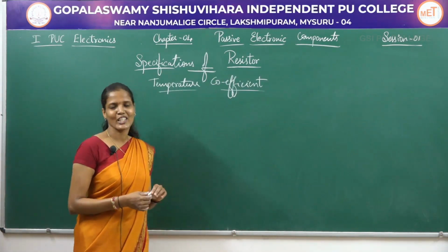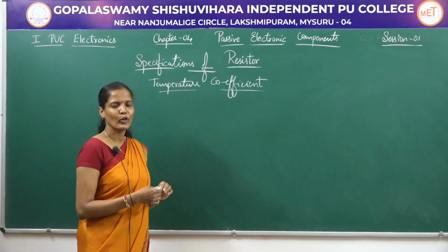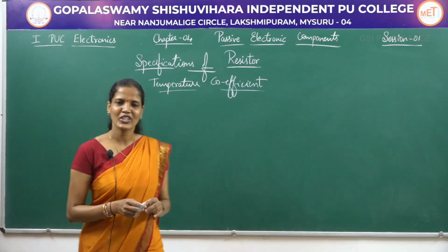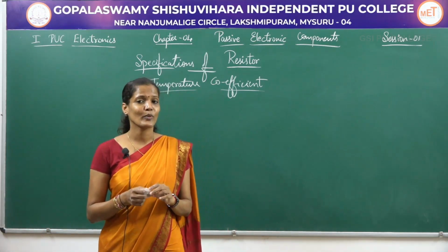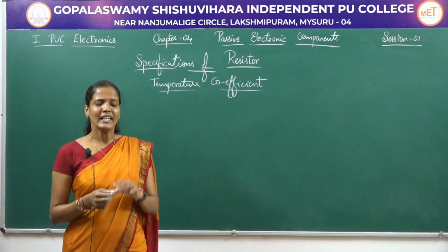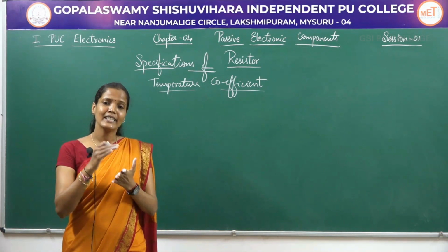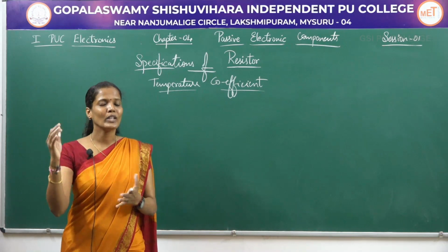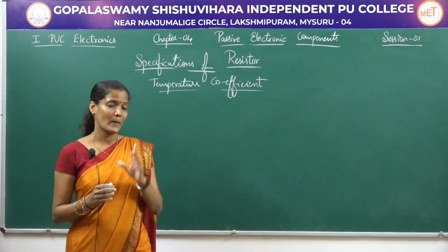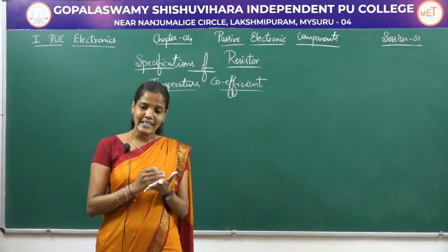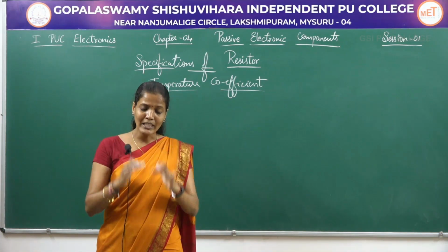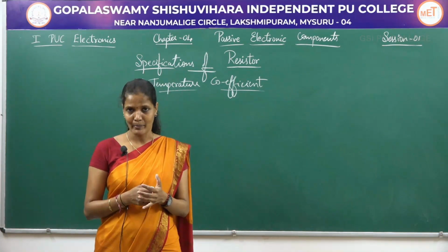The next specification of this resistor is temperature coefficient. Temperature coefficient tells us how the resistance value will vary with the temperature. In conductors, the resistance of the resistor will increase with the temperature. But in semiconductors, the resistance of the resistor will decrease with increase in temperature.